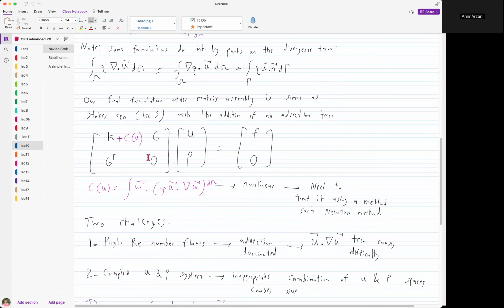Because of this and the numerical issues associated with this zero, we're going to get some challenges related to pressure. So we have to be careful as we choose the space for velocity and pressures. And as I mentioned, the easiest approach, of course, if you can computationally afford the high cost, is to use a higher order approximation for pressure, for example quadratic, and then lower order for velocity, for example linear.